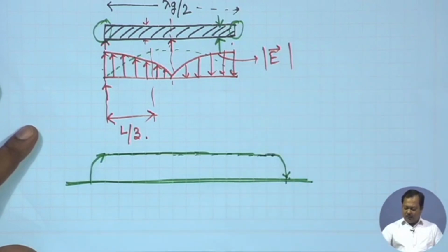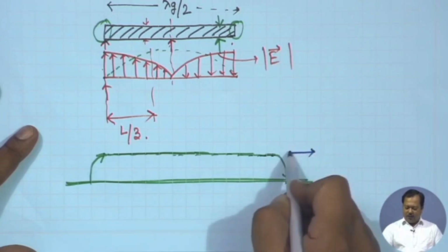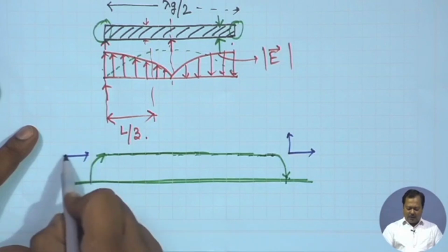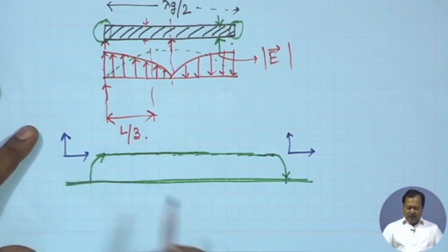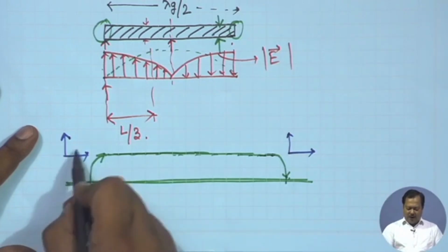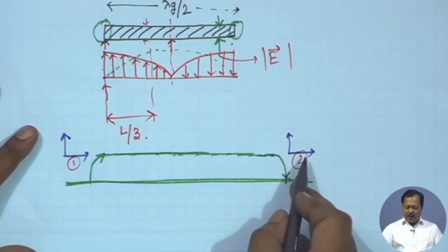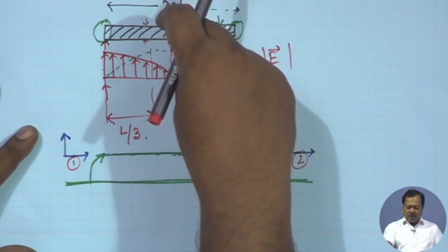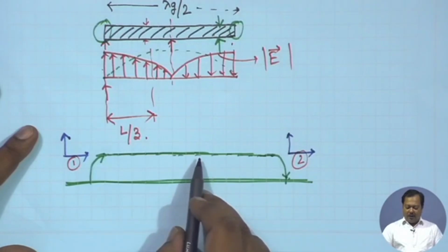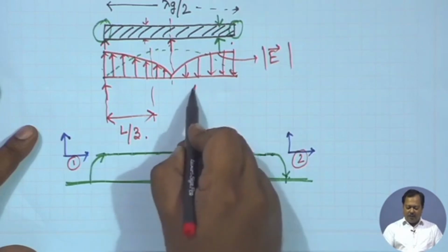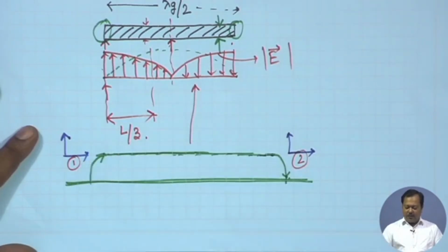Now, I can represent the fringing field along two orthogonal axes. In that case we see that these two electric field components, let us say this is 1, this is 2, are in the same direction looking from broadside, and we will have maximum radiation intensity in the broadside direction from these two fields.